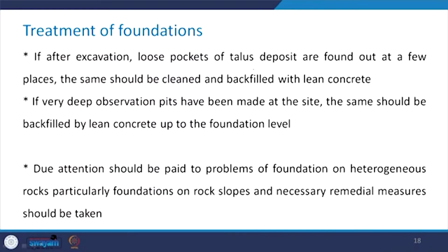That means wherever you are planning to place the base of the foundation, that should be plain. There should not be any differential settlement because of the rock and soil deposits. Now, if after the excavation, say, loose pockets of talus deposit are found at a few places, these should be cleaned and backfilled with lean concrete. In case very deep observation pits have been made at the site, these also should be backfilled with lean concrete up to the foundation level.